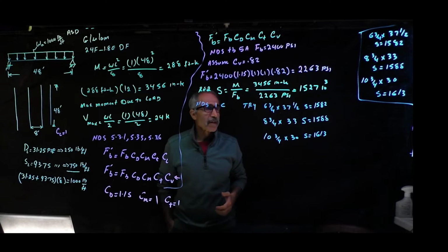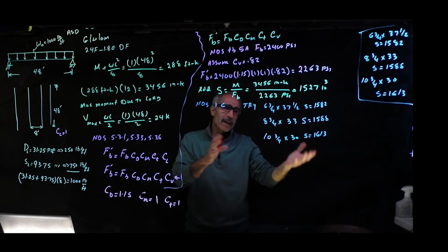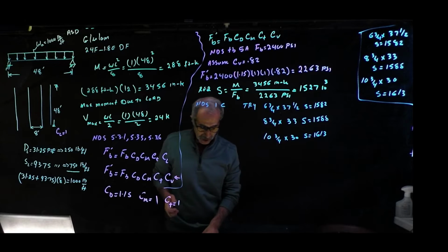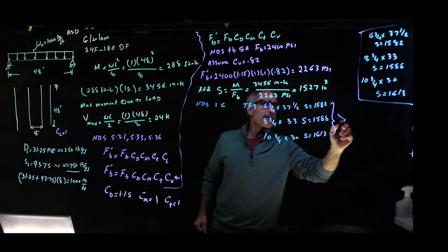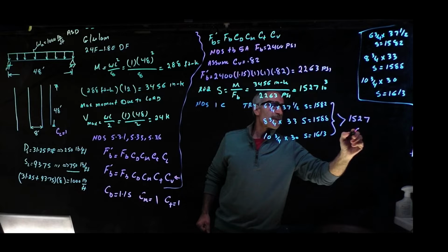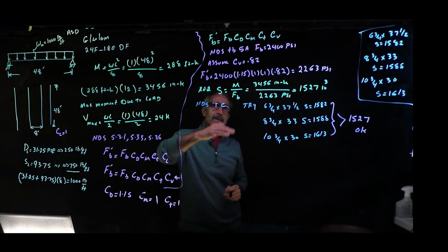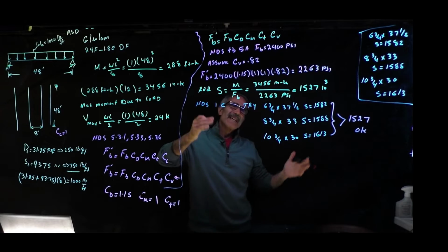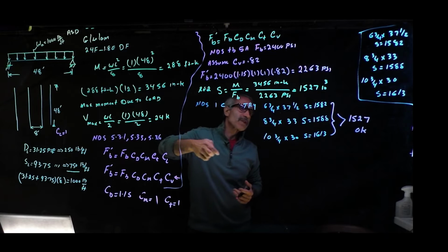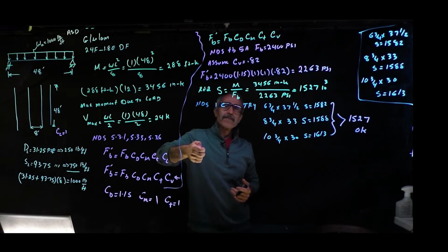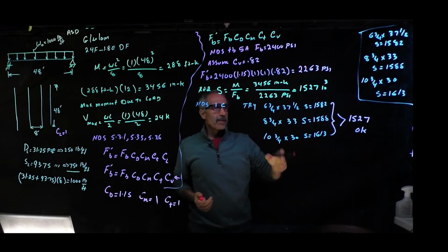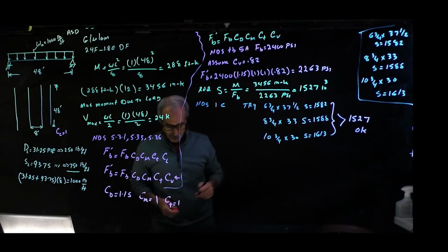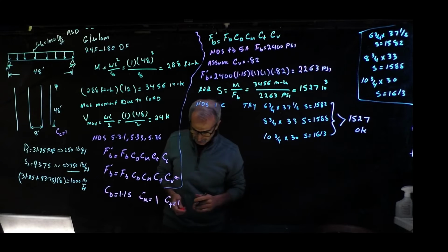And the reason I picked 3 of them is because we're doing a fire rating, it comes in handy when you look back at what we had. All 3 of them are bigger than 1527, so they basically pass the bending with flying colors. We're going to check for shear, deflection, and bearing. We're just going to use this one, but you can go ahead and practice with the other 2 on your own. Anyway, so that was the bending check, and we passed the bending check.